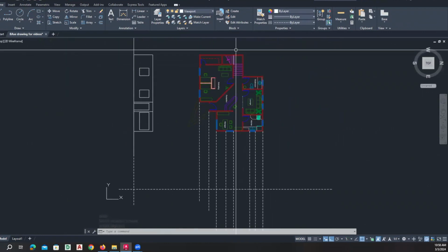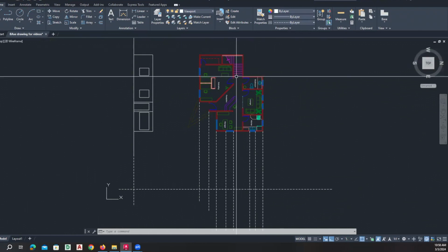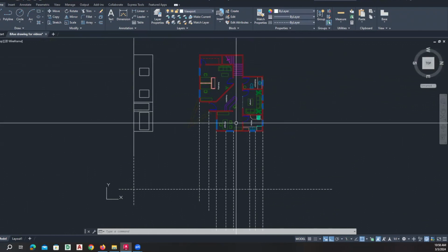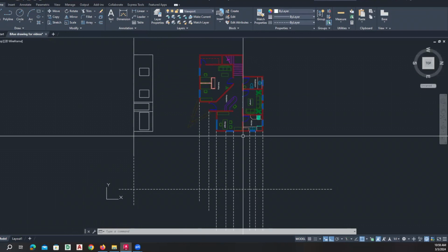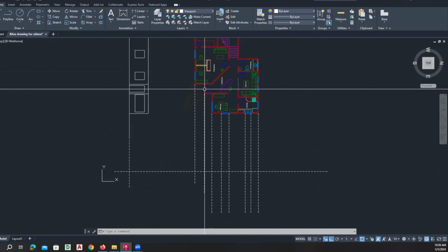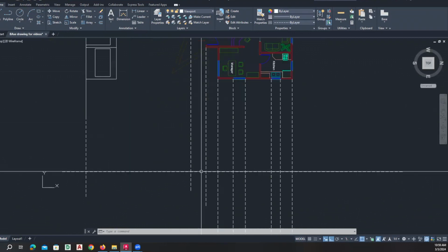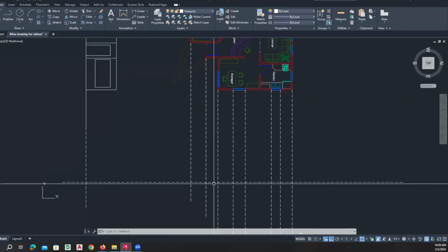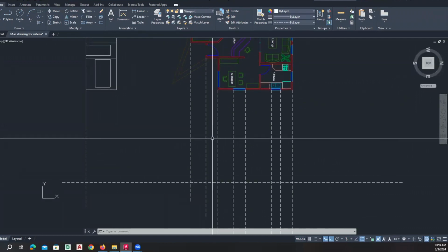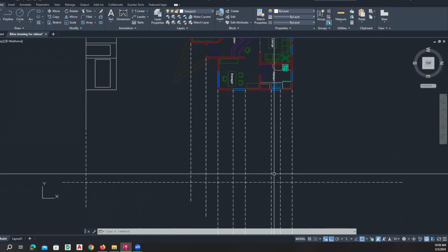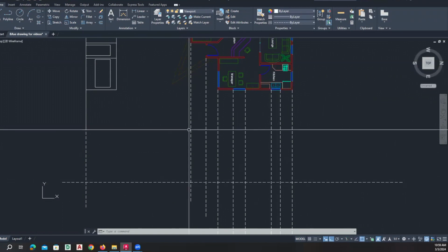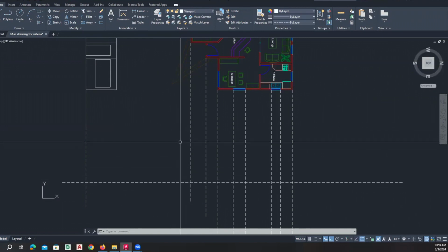It's just that for a section, we will be cutting through the plan and removing everything that we wouldn't be seeing. So if this is the projection of this plan for this elevation, what we would be doing now is offsetting this line up to the roof line. Now, we could just offset that. If we know that dimension, we could just offset it very quickly, and that's fine.